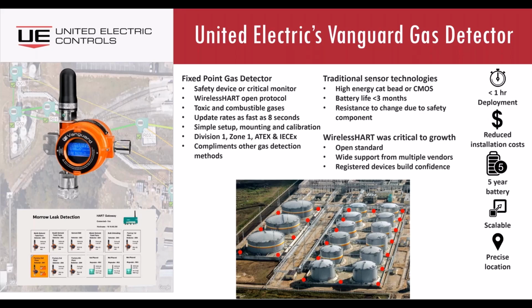The reason wireless is just becoming viable more recently is because of the evolution of technologies. One is that battery technologies have come a long way in the last decade. Sensor technologies traditionally have been very high powered and drain batteries very quickly. So you would typically have battery operated gas detectors only as personal monitors, or during a hot work permit, a handheld or an area monitor, but never really considered for long term. Those two pieces have come together now, and where we're at right now is 5 years minimum for the NDIR sensors for combustibles, and toxic gases could go longer.